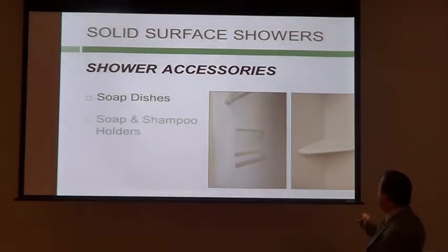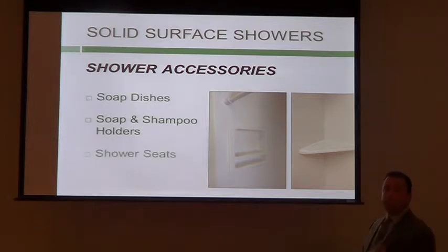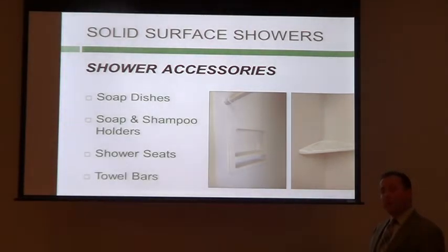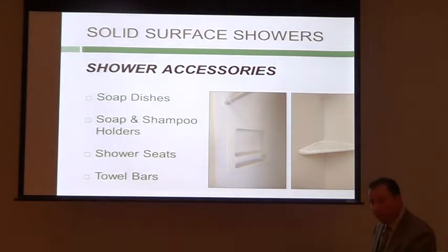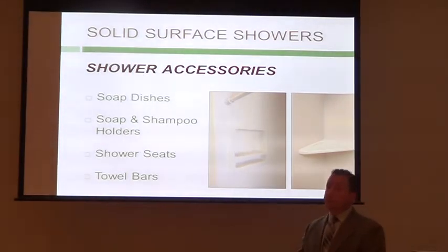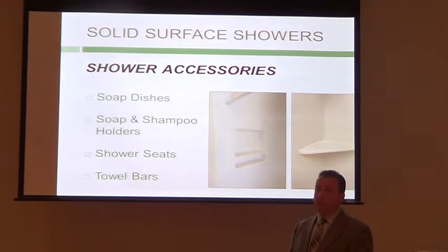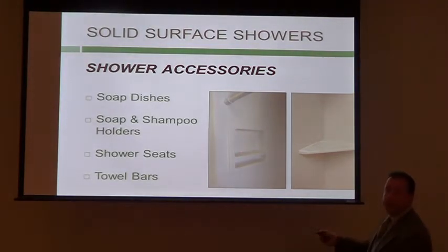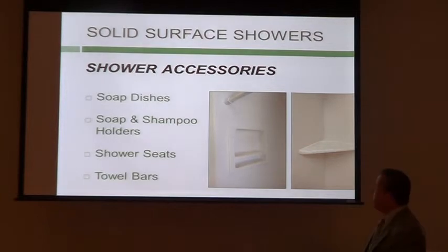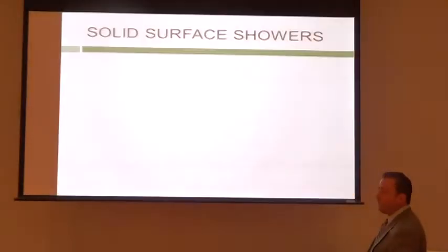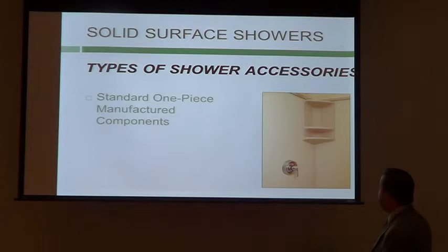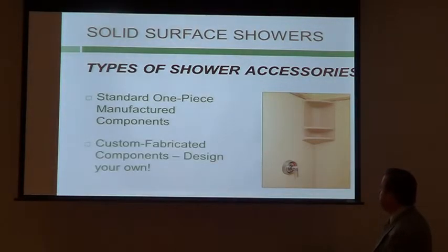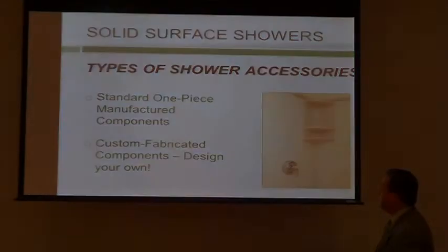Again, recessed soap dishes, surface mounted soap dishes, just something to be aware of. If you do a recessed soap dish, if that's a fire rated wall, might not be allowed. But all solid surface, especially in a shower application, is class 1A fire rated. Okay? But a lot of times at the job site, they don't want to breach that substrate of the cement board. Because to do this type of a recessed shower caddy, I'm cutting into the substrate. Shower seats are available, towel bars. You can design your own, because a mold can be made for any shape or size.